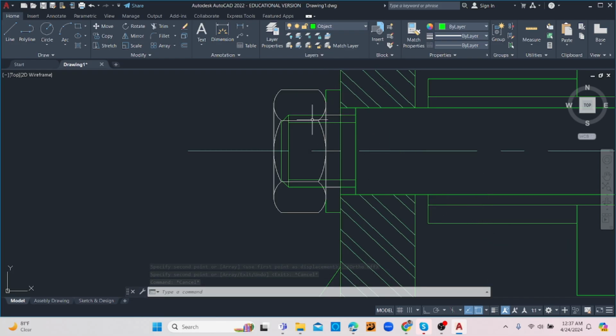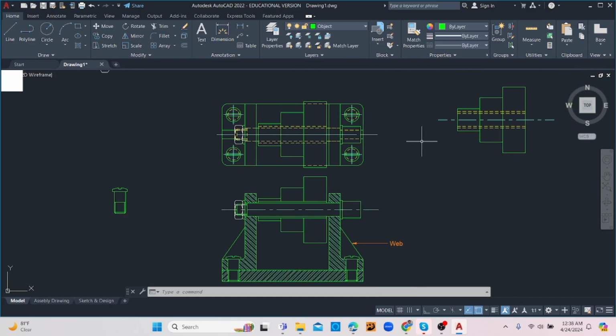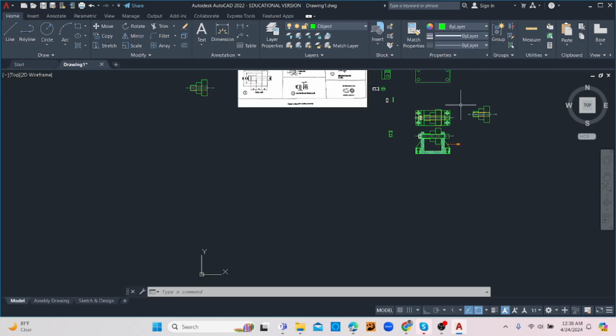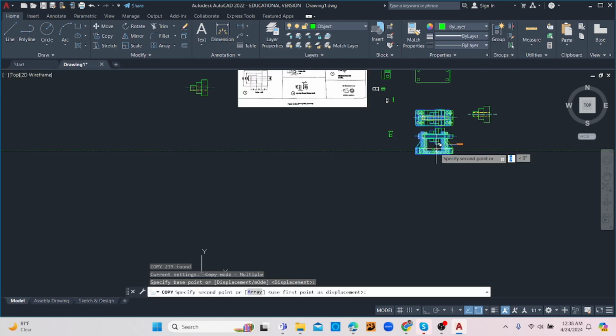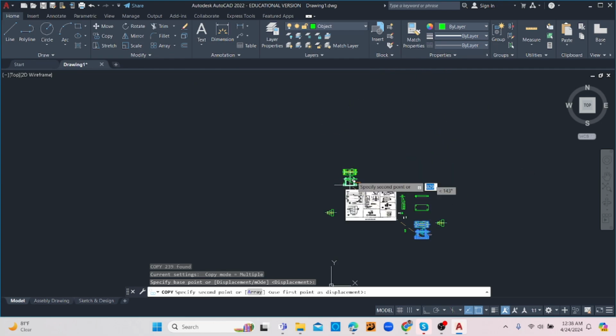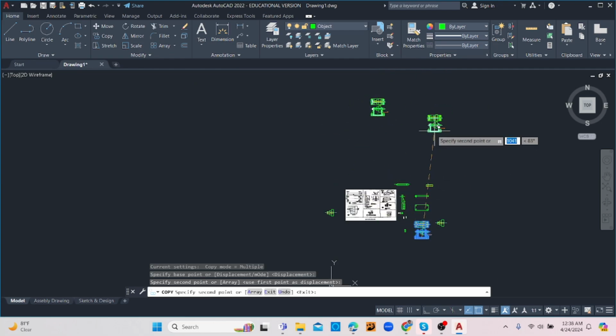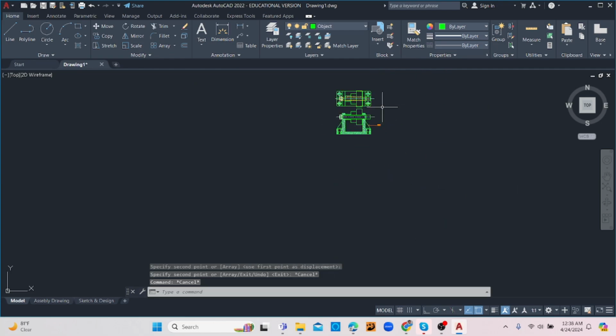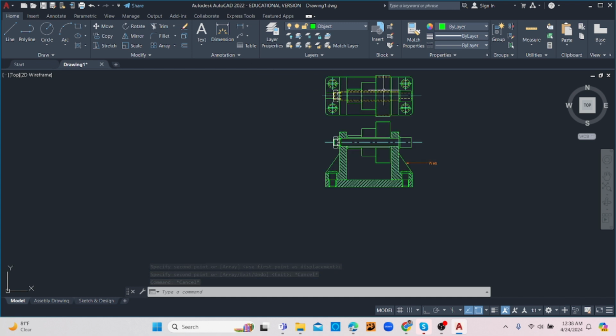Alright, now once that is in place, it's time for us to neat up our drawing, finalize some other stuff with the drawing. So let's now grab onto our two drawings because we're basically finished. It's just that we have a lot of time now to finalize our drawings. So for example, adding the names, dimension, sorting out some of these hidden features, so on, sorting out some of these hatched features. So we're going to be hatching our pulley, so let's hatch our pulley as well.